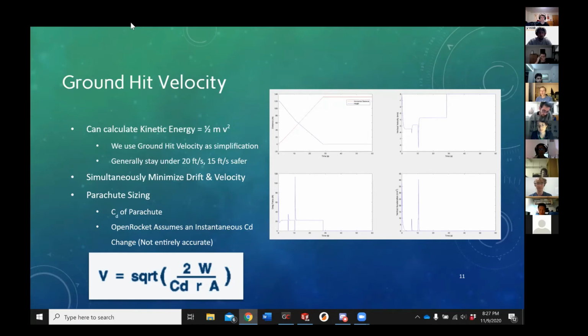So if you have a big wind, say a 10-mile-an-hour wind, or here, we'll call it 10 feet per second, that's easier, and say it takes 20 seconds for your rocket to get down, then it's traveled 200 feet sideways. Depending on your launch site and what's in the vicinity, that horizontal travel might not be acceptable.